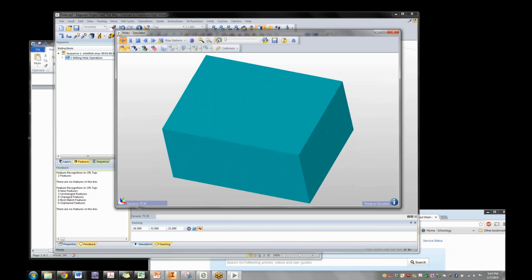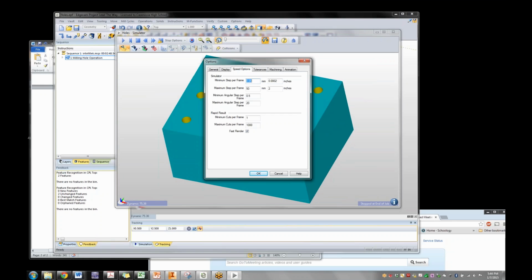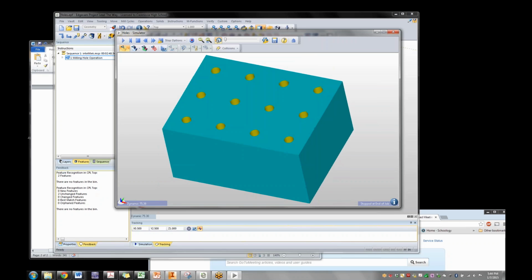The one that IntelliTech machines cannot understand the code for is chip break. It'll put in a G code that it doesn't understand or can't interpret. You may have to change your millimeter too. I don't know why.